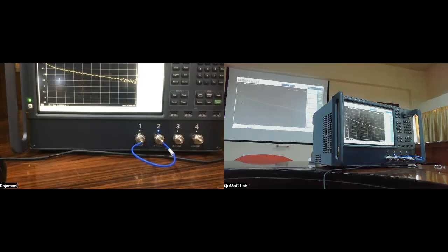One, that there is actually absorption in the transmission line. So this coaxial cable, which means the power is actually getting absorbed inside the cable as it's traveling, which is not a lossless transmission line. But it could also be due to reflection. Okay. So in order to know which one is that, you have to look at the reflection. So if at 20 gigahertz the reflection is not very high, because 1 dB is a small number, but it's not insignificant. Remember, 3 dB is about a factor of 2 loss in power.